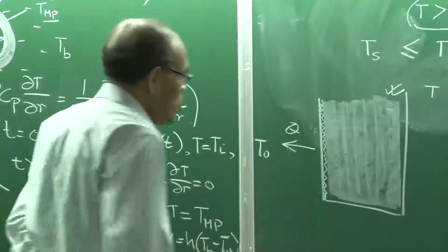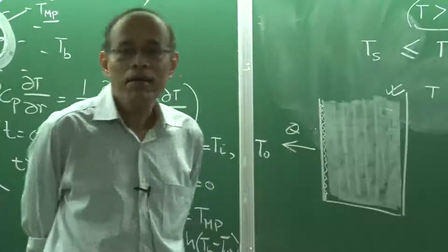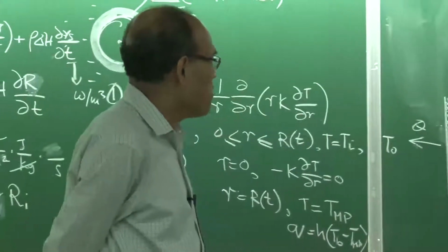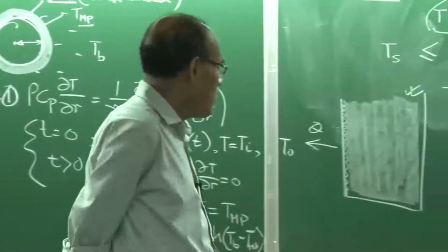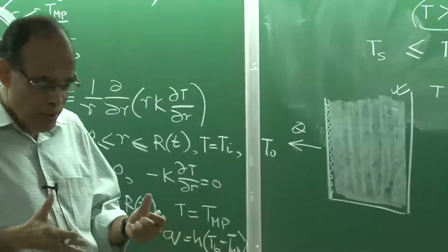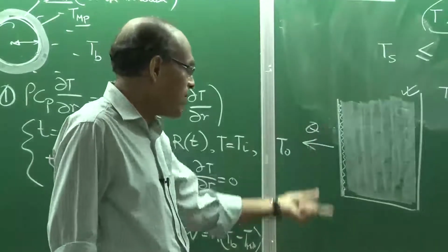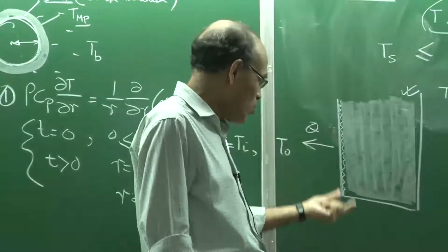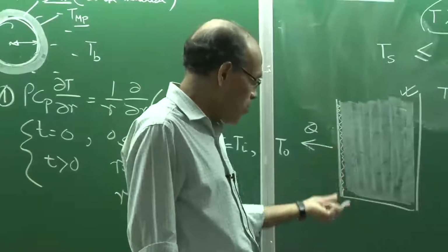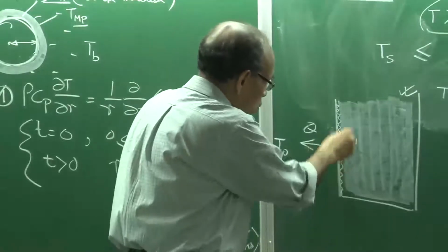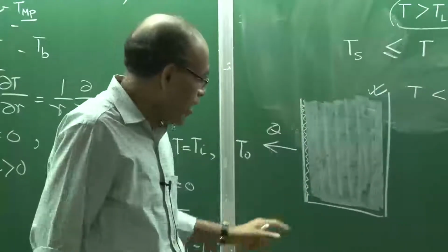So typically what we do is add mold powders, which are low melting point oxides, basically oxides of silica mixed with some alumina, and when they form compounds, the melting point undergoes depression. Various kinds of oxides are there in different proportions, mostly silica, alumina and calcium oxides, iron oxide sometimes also, potassium oxide, sodium oxide, etc. When you pour these low melting point oxides, they fill the gap and displace the air.